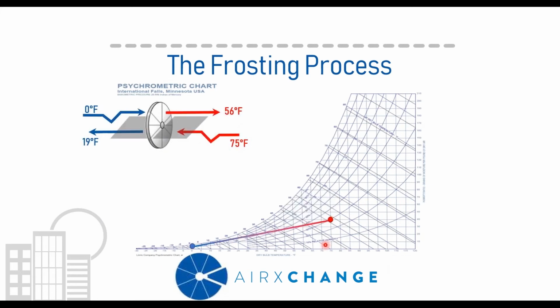Now let's take that same example and lower the outside air temperature. Let's go to 0 degrees. And let's plot that same point. Plot the supply leaving air, representing that red dot, and now the exhaust air. You can see that the process line comes closer to the saturation curve, but still hasn't intersected it. So theoretically, this process shouldn't form frost in this operation. And this is even with temperatures that are significantly below freezing.